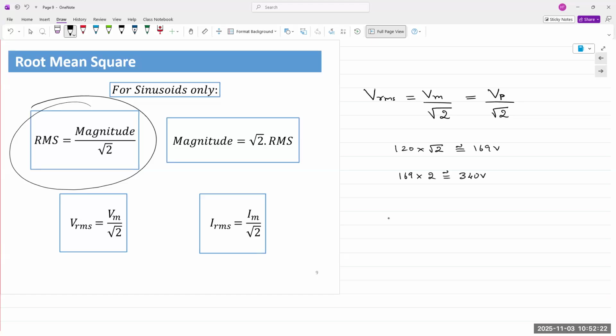That's the total peak voltage, meaning 60 times in 1 second, the power outlet goes to a value of 169 volts, and it also goes to a value of minus 169 volts. Because of the 60 hertz sine wave in North America, those fluctuations happen 60 times in 1 second.